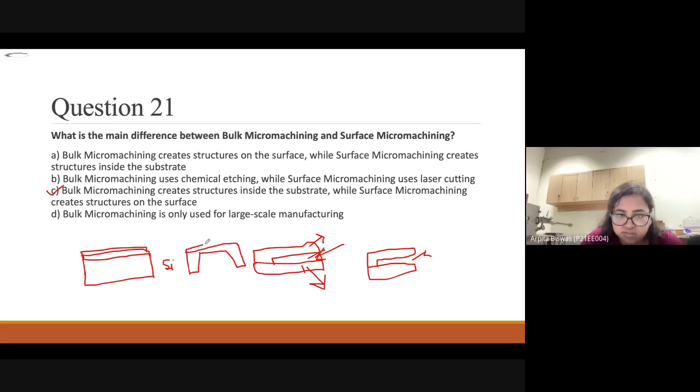Then the oxide layer is present, and on the oxide layer, to measure how much the electrical property changes, you can also add a sensing layer like ZnO or something else. For measuring purposes you also deposit some electrode there, all these things.